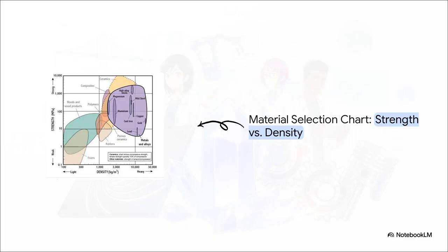And this is where the process gets beautifully visual. Engineers use what are known as Ashby charts as maps to instantly screen materials. By plotting something like strength against density, where each bubble represents an entire class of materials, they can just draw a line. If our constraint requires a highly specific strength-to-density ratio, everything on the wrong side of that line, like woods, foams, or unalloyed polymers, is immediately visually eliminated. It saves a massive amount of time.